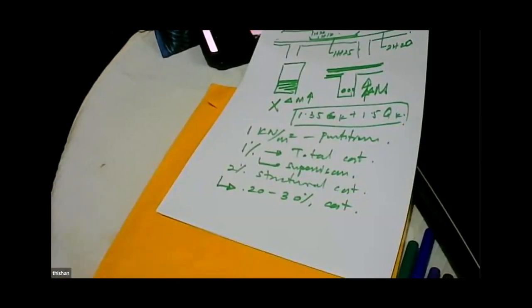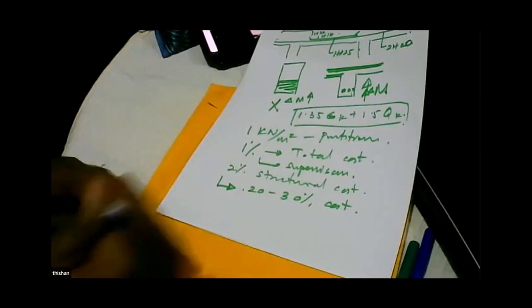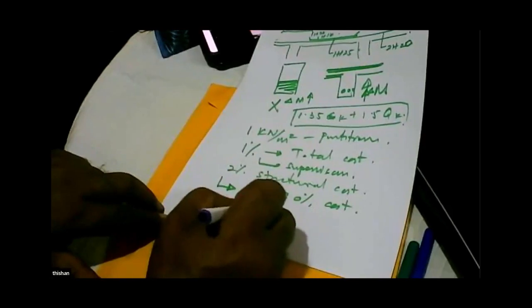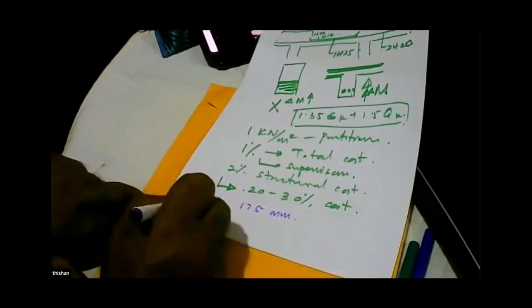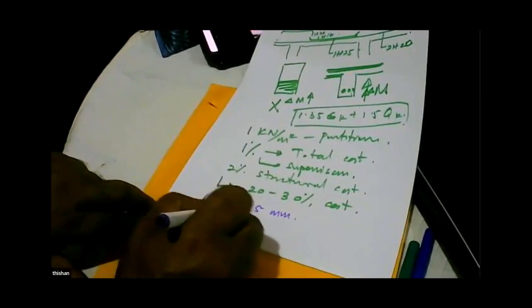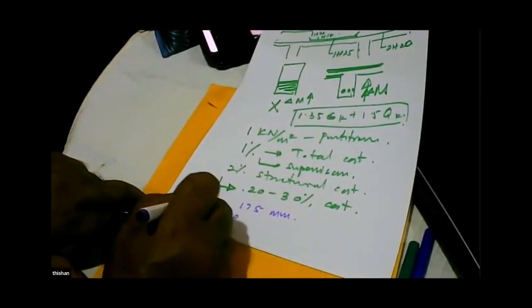Okay, sir. And sir, what can we do to take these value engineering tips and things to practicing engineers? I mean, from this lecture series. Actually, now one by one, I'm going to disclose a different way of thinking about structures. That different way of thinking is the one that value engineers use. So for a value engineer, a slab cannot be just 150 or 170 millimeters. It can be anything like 130, 140, 150. And he will try his best to go for 130.